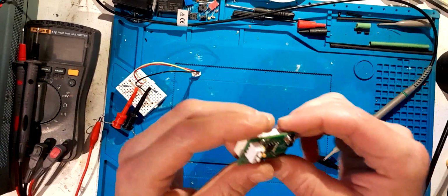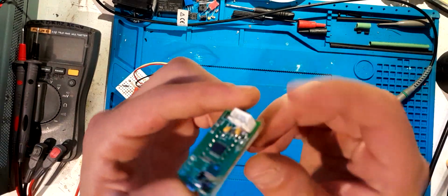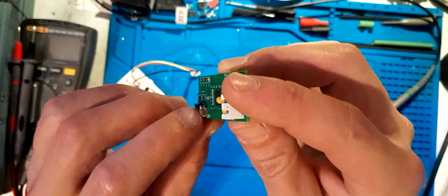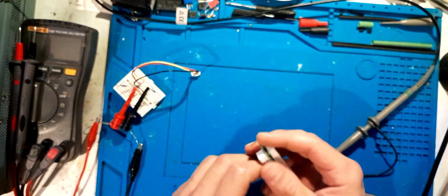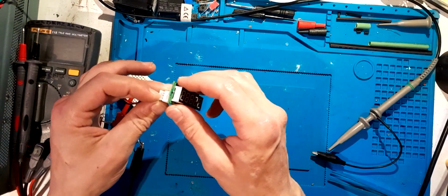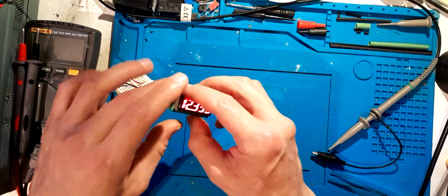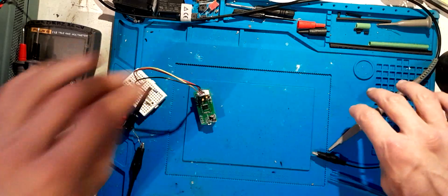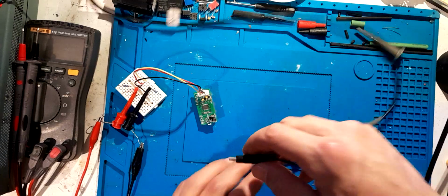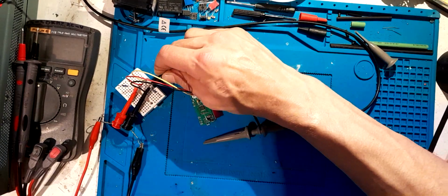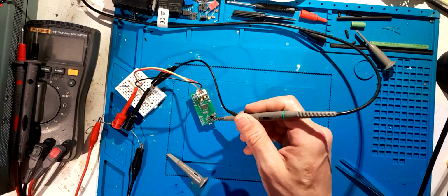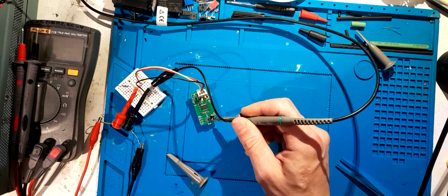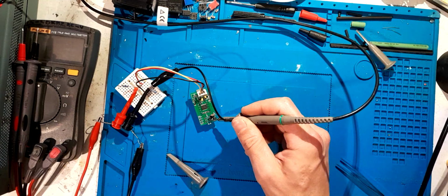So there you have it, guys. There is two caps stacked there, and now a diode pointing from the output back to the input. So on power down, we can't risk damaging our regulator. I'm just going to check one more time for ripple in case that diode has formed a path for something that we don't want, but no, it's all gone. It's great.